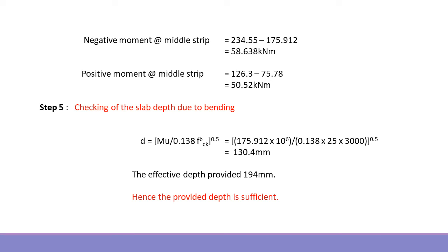So our effective depth provided is 194 mm. We can provide 194 mm, and the required is 130, so it will be safe for the slab. Hence the provided depth is sufficient.